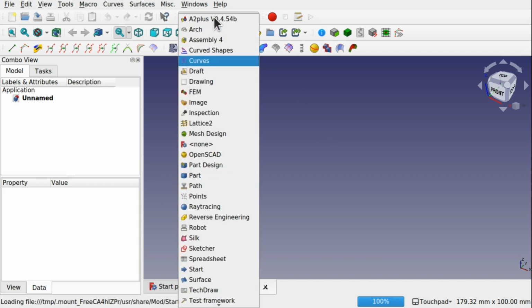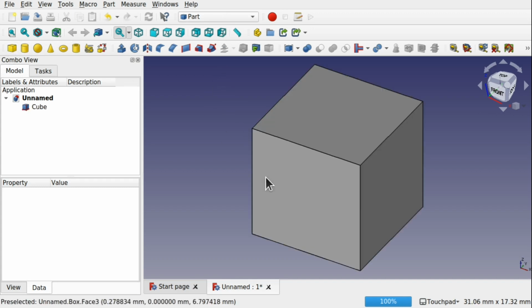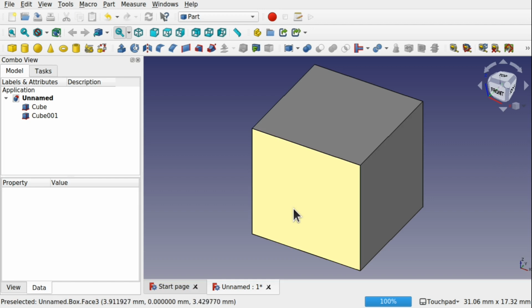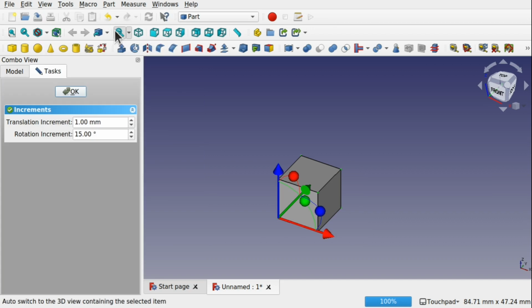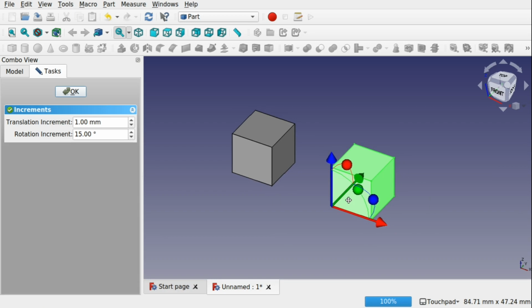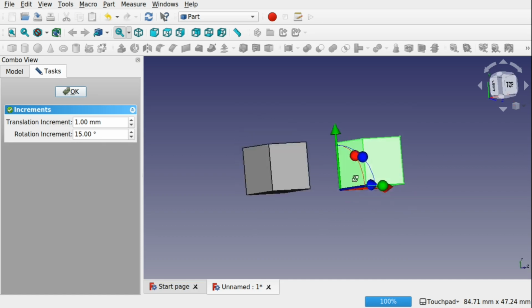We're going to first tackle the easy one, which is the part, and we're going to demonstrate how that tool works. So I'm going to create two shapes on here. I'm going to create two similar shapes. Now I can use the primitives along here, or we can use a sketch. We're going to go for a primitive first. So we're going to just create a cube on there, and I'm going to create a second cube as well. This is just to show you how this blend tool works. I'm going to transform one, and we're just going to keep them in line for the time being, keeping it simple so we understand how that tool works. We'll grow how complex this is as we go along. So we have two cubes,